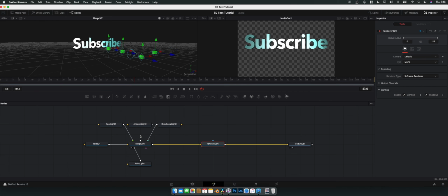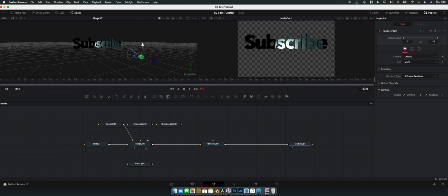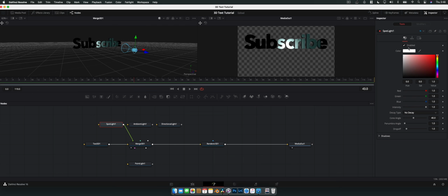So I'm gonna do that by disabling them all, except for the ones that we're gonna look at. So a spotlight. We have this blue diamond, which is the light source. We have this little cone here, that is the light direction, and it acts just like a spotlight you would see in like a theater. And as you can see, as I move it in and out, we're getting a controlled light source here, similar to the Pixar light. Now, if I have the spotlight selected, we can change the color of the light, so it can be a different color, and that's going to dynamically change with the color of the text. So if I change it, we can get a little bit of light there.